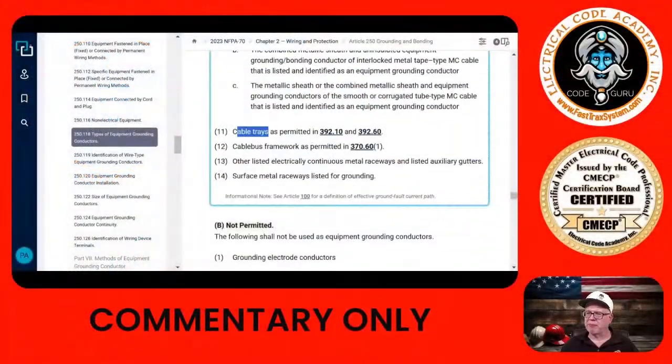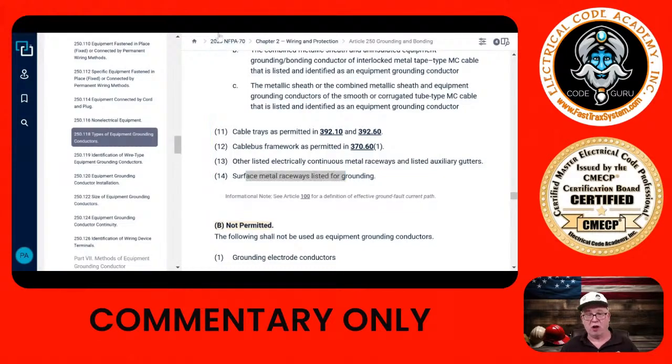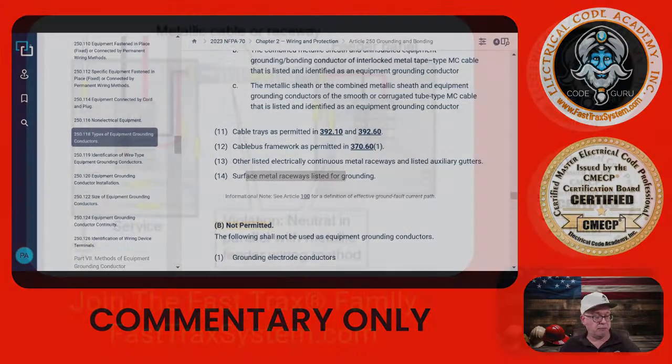Okay, so cable tray, that's obviously not what's in our drawing. And of course, cable tray has to meet these requirements as well, has to be listed for use in grounding and bonding applications. They're out there. You just have to find them, but we don't have a cable tray in this image. And we certainly don't have a cable bus. We don't have anything like auxiliary gutters and things like that. And we're not talking about surface metal raceways. Okay, so absolutely not in this scenario.